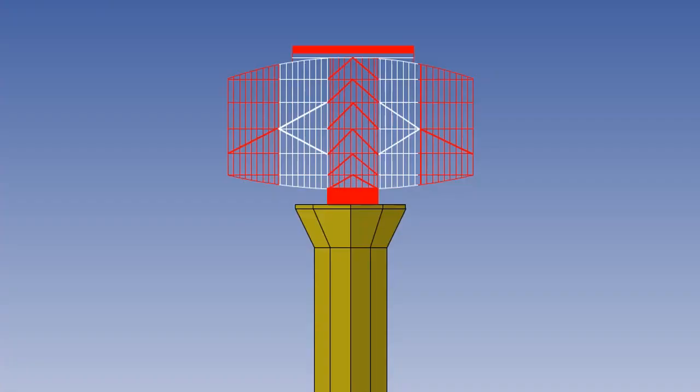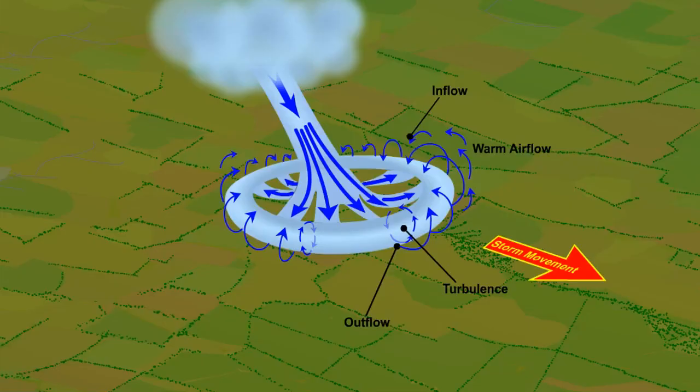If at any stage of flight any moderate or severe turbulence, wind shear or microburst is encountered, air traffic control must be informed with details of location and severity of the phenomena to allow them to issue warnings to other aircraft. Ultimately, awareness of the phenomena, which may or may not be visible, must be backed up with prompt and positive action should you find yourself experiencing the conditions caused by a microburst or wind shear.